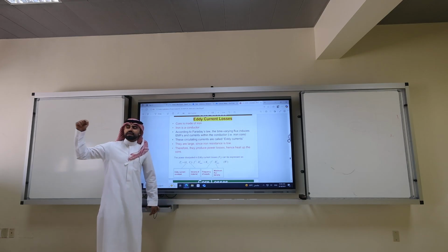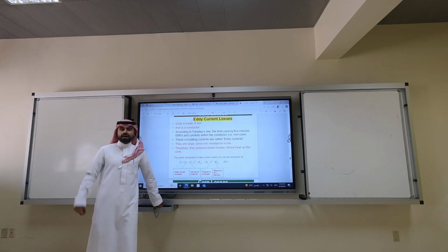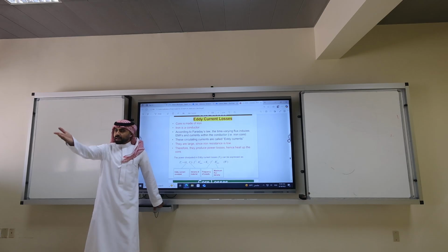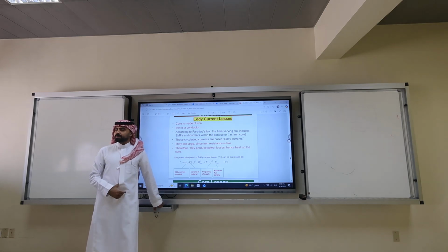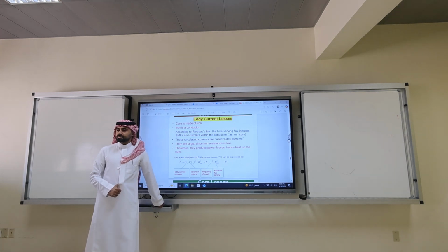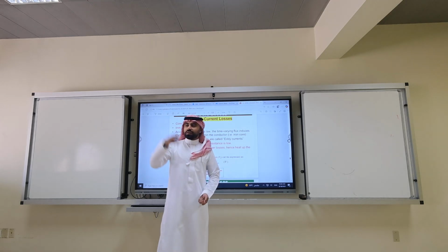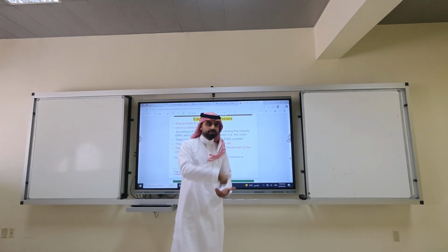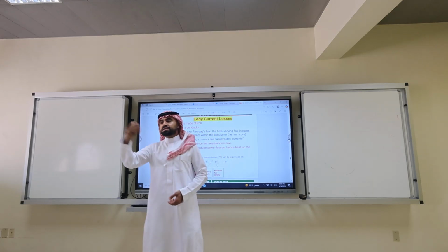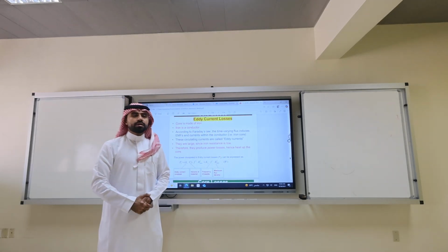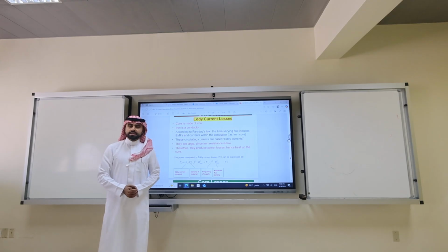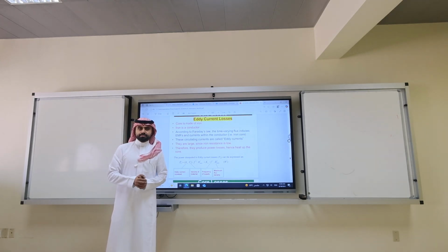So, if I apply AC current, what will be the flux? What will be the flux? DC or AC? Think. What makes more sense? AC. So, if the input current is AC, your flux should be also AC. So if it has RMS, the flux should have RMS. If it's DC, the flux should be DC. It is a flux, but it's going to be constant.